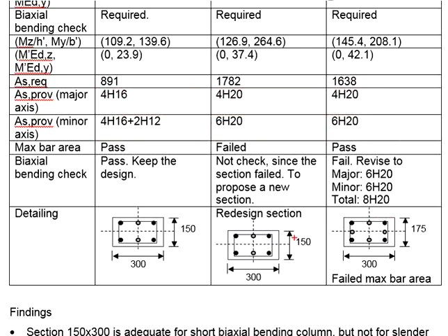Therefore, it is important for you to sketch the reinforcement and then to see the amount of reinforcement bar effective in the non-critical axis. In this case, we observe that we propose 6 units of reinforcement bar in the minor axis. It eventually ends up to be only 4 reinforcement bar effective to the major axis. This you have to be careful.